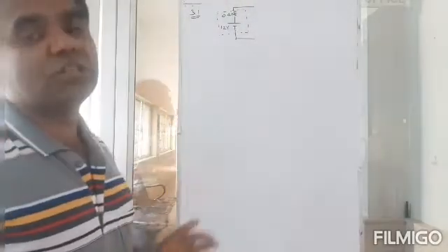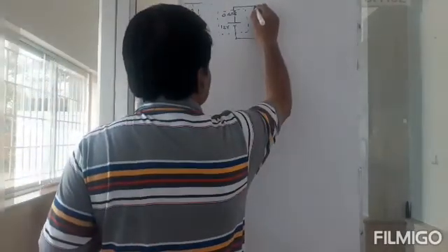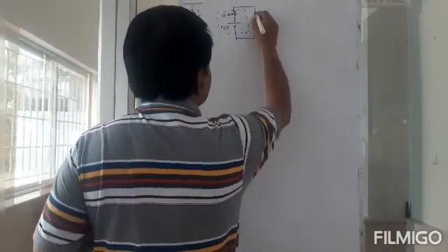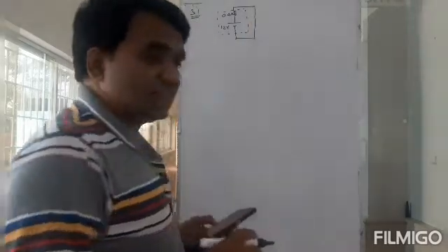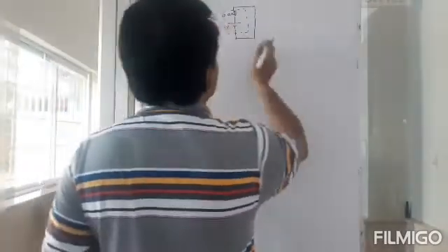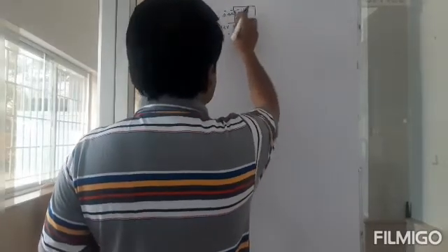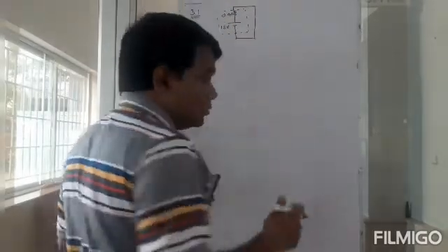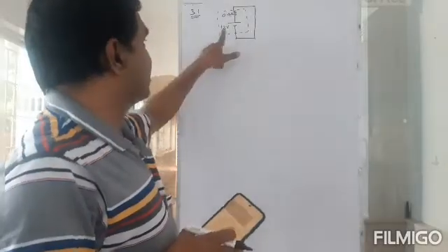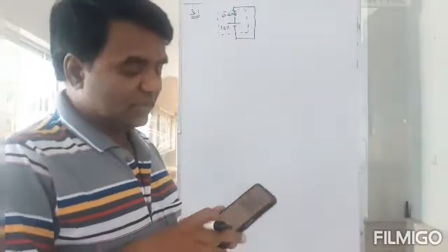But then there is this internal resistance which is part of the battery, and now I am going to short it. So I am not going to have an infinite amount of current. My current is going to be high, but it's going to be limited now. What is the current now? Well, the resistance is 0.4. I can do it straight away. This is 12 volts and then 0.4 ohms. 12 by 0.4 will give me the answer straight away.